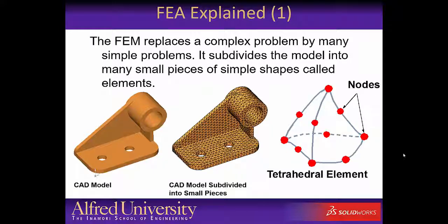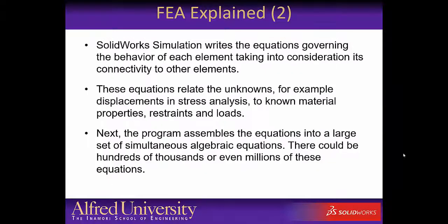The behavior of an element is well defined by analytical mathematical expressions. SOLIDWORKS writes the equations governing the behavior of each element, taking into consideration its connectivity to the other elements. These equations relate the unknowns, for example in stress analysis, the displacement of each node, to known material properties, external restraints, and external loads.